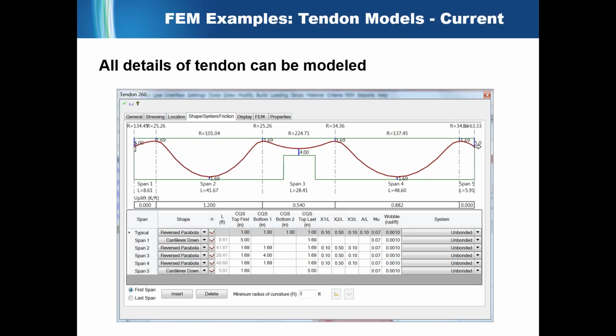And when you're modeling these tendons, these are true construction elements. So they are modeled from end to end, and they have a lot of information stored with each one. So for example, in this tendon, and those of you who are used to Adapt PT-RC might find this image somewhat familiar. It is kind of a duplicate in some ways, but it's important to note what's shown here. For example, you can see that this end has a dead end, whereas this side is a live stressing end. You can see the CG values indicated.